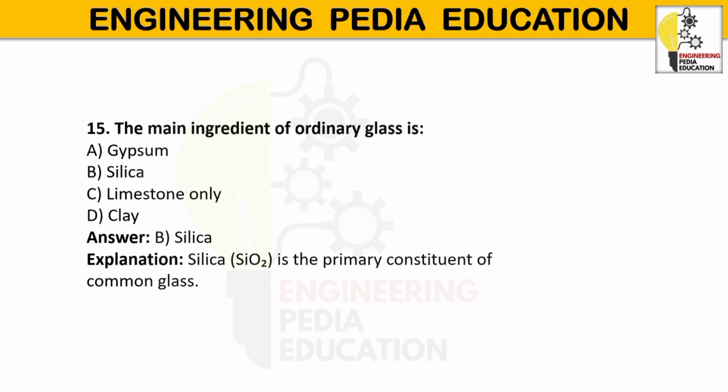This glass is transparent, allowing natural light to pass through, which makes interiors brighter and reduces the need for artificial lighting. It has a smooth surface, is easy to clean, and is available in different thicknesses and sizes. Ordinary glass has a major limitation. It is brittle and breaks easily under impact and thermal stress. It forms sharp, pointed pieces which can cause serious injuries. Because of this, it is not considered a safety glass.